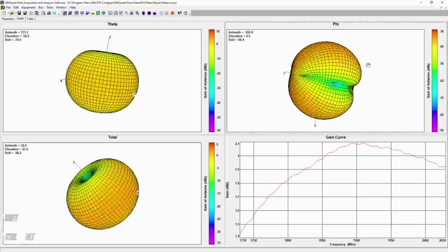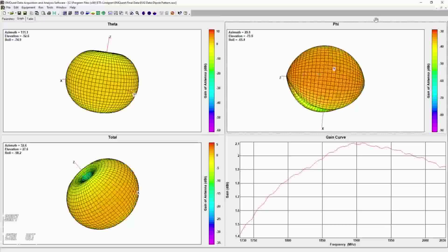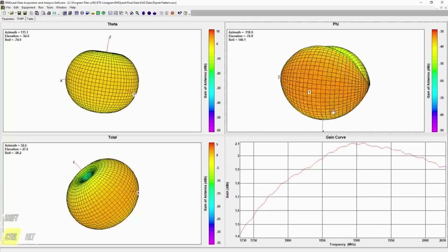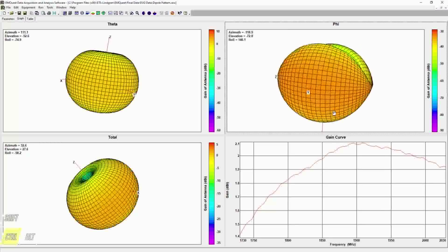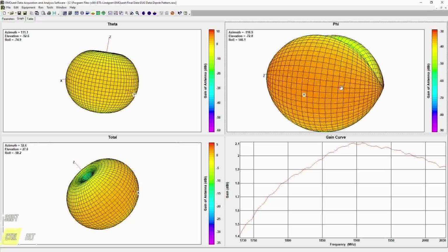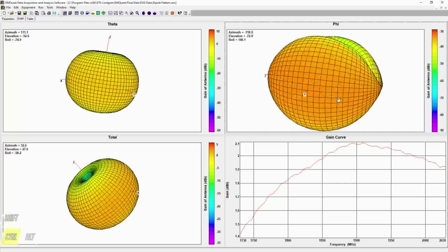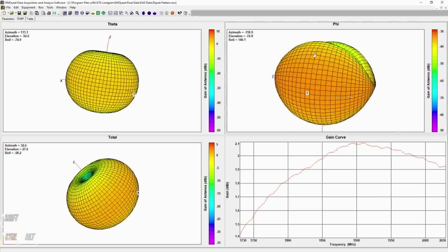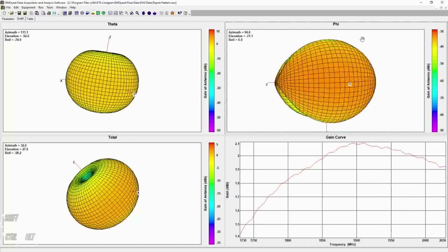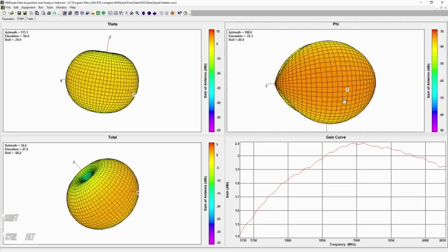The more useful thing is, for example, let's say I turn this thing this way, and I wanted to make it a little bigger. Well, if I hold Control and drag, that's actually a zoom on the plot. So that would let me change the size of the plot in the window, and depending on the aspect ratio of the window, how I've got things set up, I can actually adjust these plots around to look exactly like I want them. And then, of course, I can still copy and paste and put that in an external document or whatever.